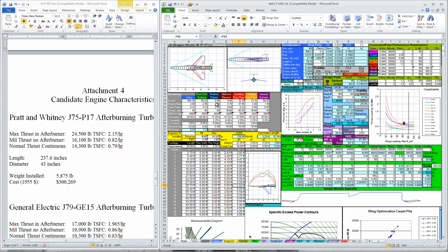First, let's give it flaperons instead of flaps and ailerons. That way we can put the actuators inside the fuselage and we don't have to put any actuators in the wings. F-104 had some crazy aileron actuators inside the wings, and we don't want to do that if we don't have to. This will keep the airplane simpler, easier to maintain, and more reliable.